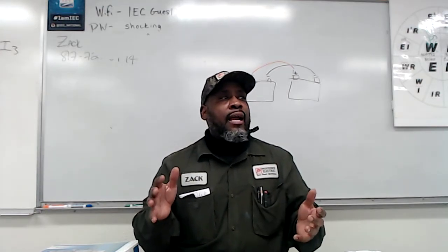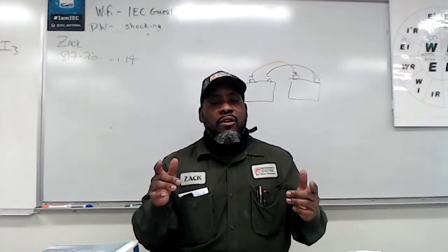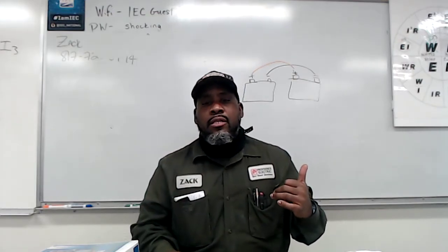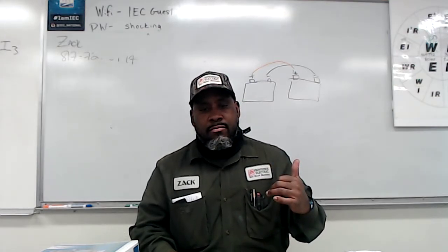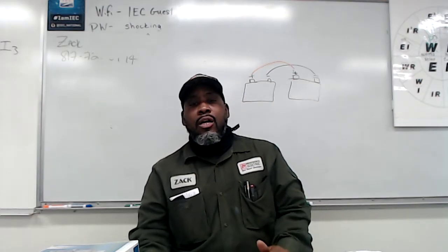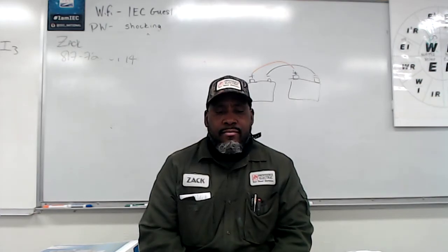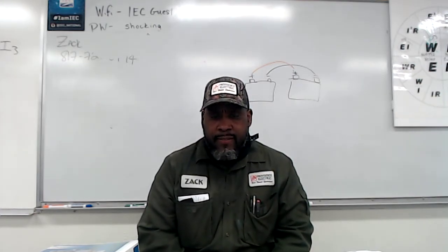So all we're doing right now is figuring out this truck needs 24 volts to work. All we're trying to do is figure out what configuration gives us 24 volts. Well, explain to me. It all sounds good. 1, 2, 3. It's in series. Which one? Prove it. 3. Because the negatives. So 3 is in series?